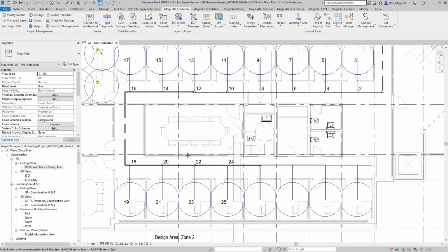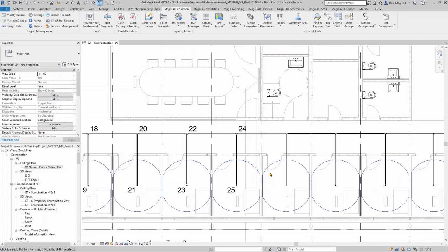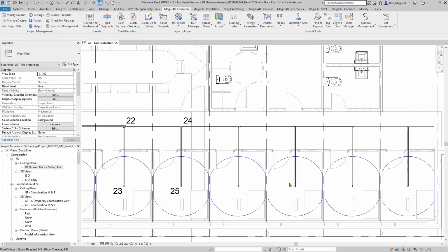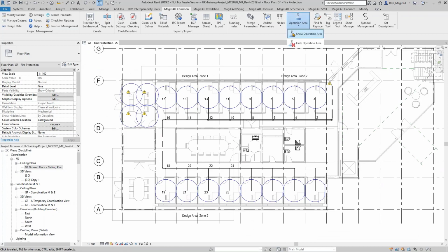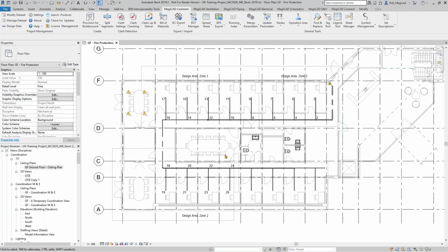So it's quite a handy tool again to have, just as a double check visually to see if the sprinkler heads that you're putting in do match. And obviously if you want overlapping sprinkler head coverage, then if that was like 4 in a row in a space, these would just slightly overlap here and here. So great, again you can use that to determine that as well. If you want to turn them off, then just press hide, and in that view it'll just turn them all off again like that.